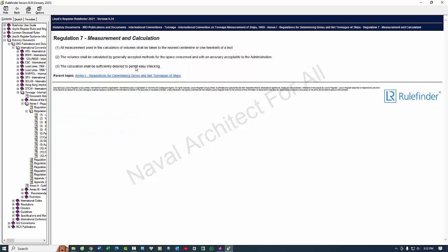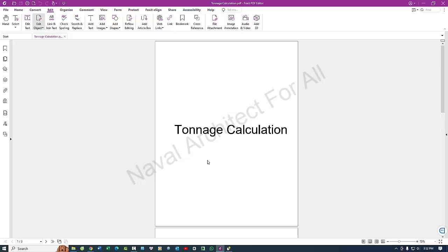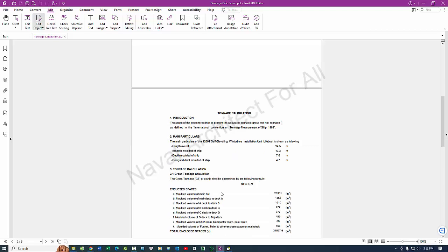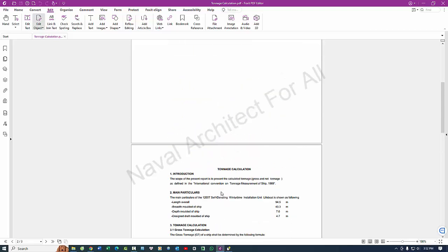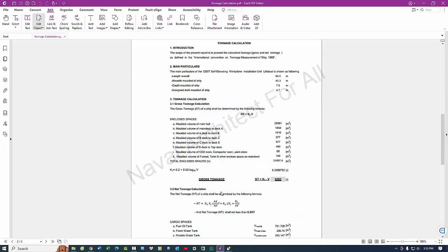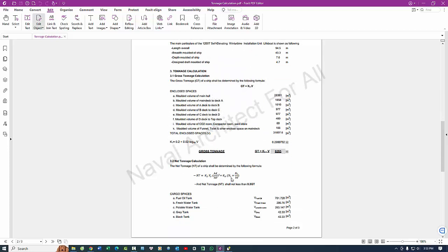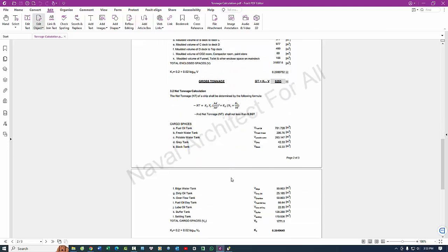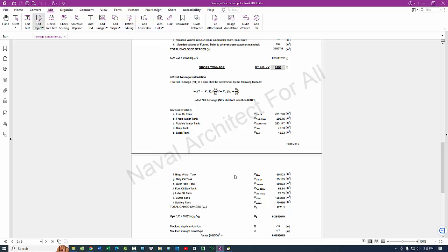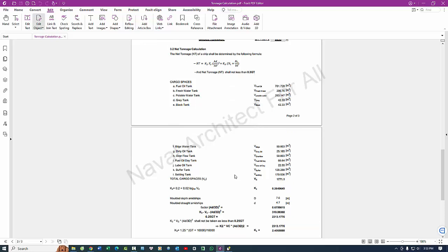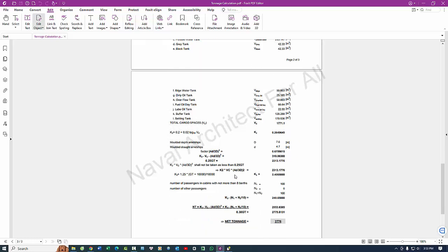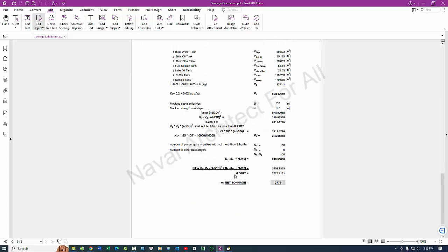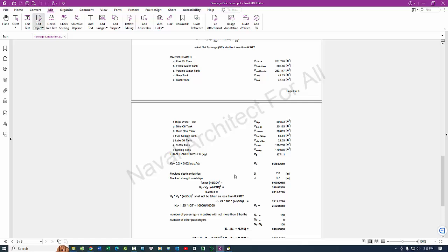5. Cargo operations. Deadweight tonnage informs shippers and operators of the maximum weight of cargo, fuel, provisions, and ballast the vessel can safely carry. 6. Insurance and commercial contracts. Tonnage figures are crucial for underwriting insurance policies and drafting commercial contracts. They affect premium calculations and contractual obligations. 7. Design and stability assessments. Tonnage calculations help naval architects and marine engineers design vessels that meet stability and performance criteria.